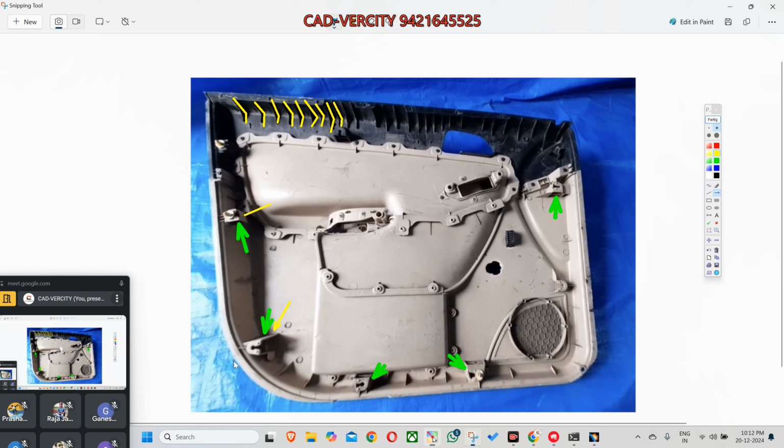Now you got the point: what is inside undercut and what is outside undercut. Now same situation, see here. The doghouse here is the wall, and the facing of this doghouse is inside over here. So you will need a lifter, because your lifter is going to slide on this plastic material. Here you can see, is there any plastic material? A slider is just coming out from the undercut.